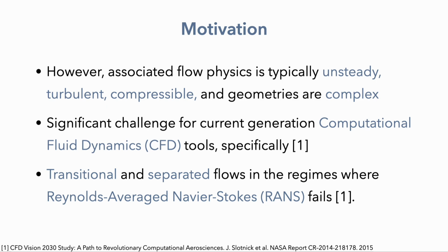And if you're familiar with conventional CFD, you'll know that this introduces the requirement for turbulence modeling for the unresolved Reynolds stresses. And it turns out that these turbulence models, which are based on heuristics and experimental correlations, really struggle, particularly in regions where we're dealing with transition and separated flows.